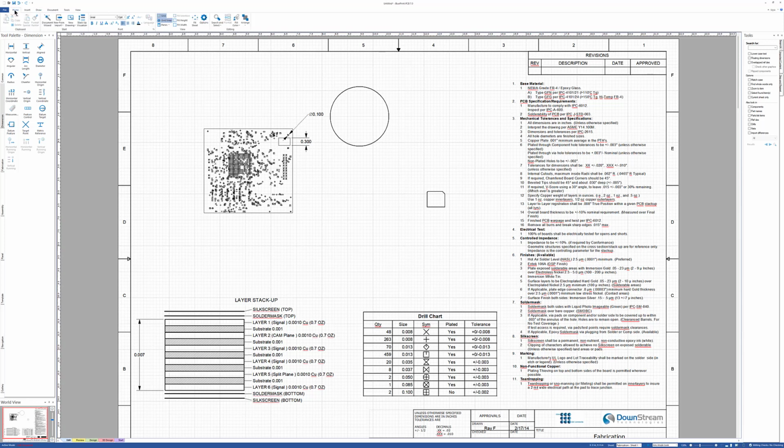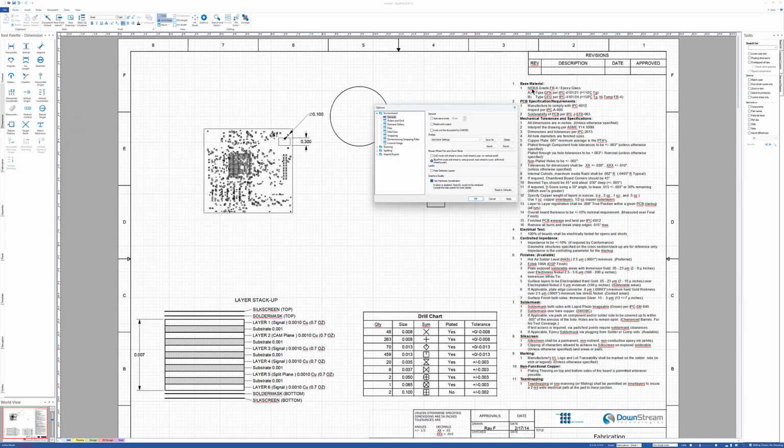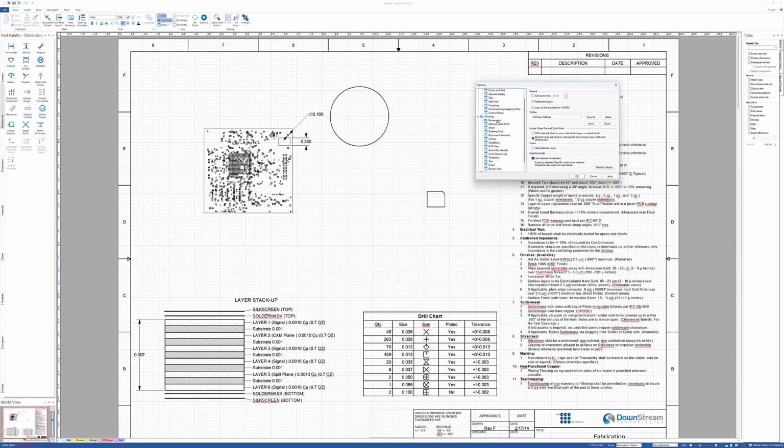If we were to go to home options and dimensioning, you would start to get an idea of some of the dimensioning options that we do have. And one thing I will say in here is it's broken down by dimension type. So you can have different dimensions, for instance, for diameters or radians or regular English or metric units. So there's a lot of options in here. Where they're placed, how they're placed, do you add tolerancing info, do you show your units, do you suppress zeros, which units are you using? You're using your defaults or you're using some other dimensions.